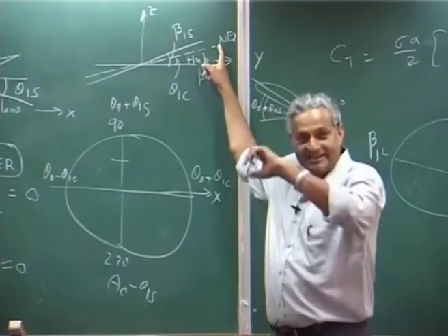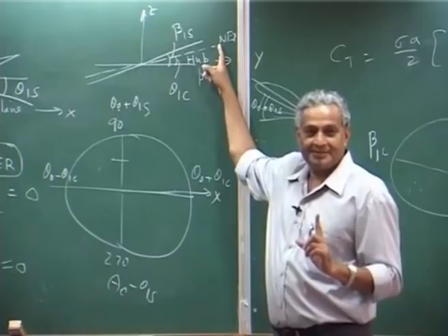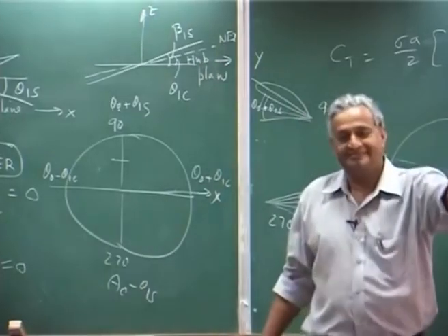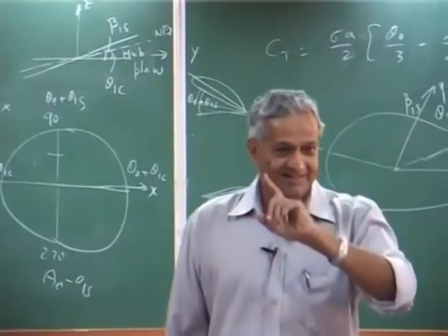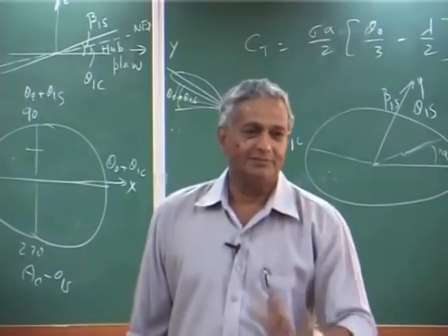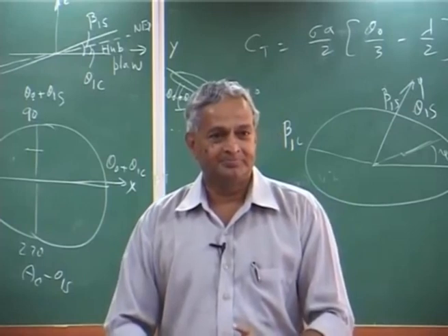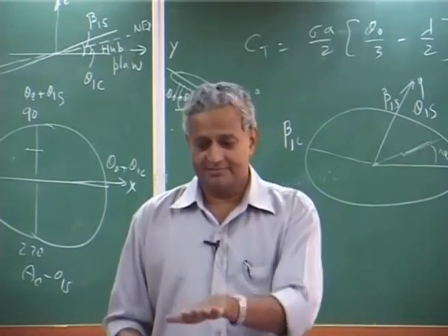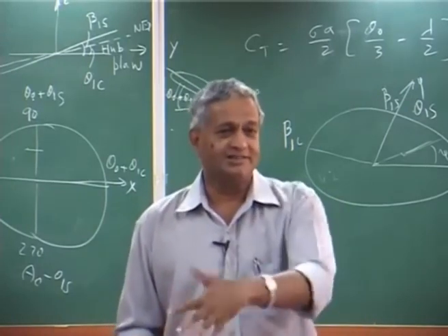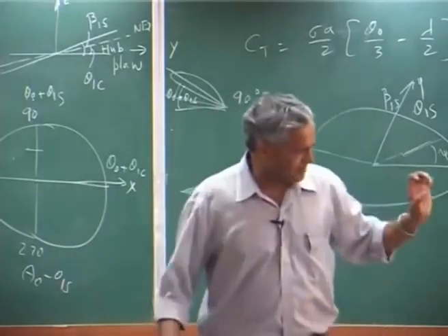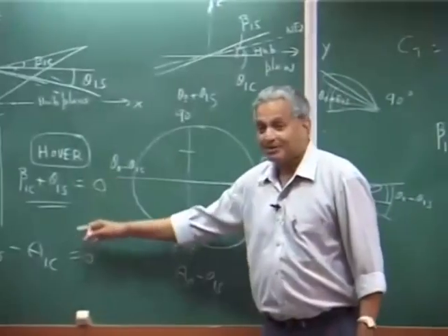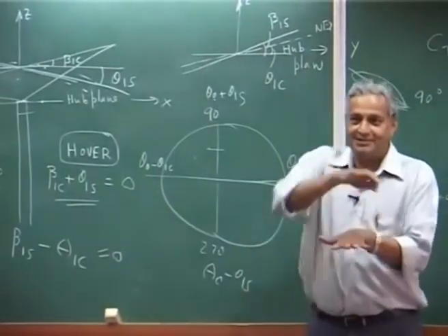And because of the blade dynamics, the tip path plane tilts. Okay. He does not tilt the tip path plane, he tilts only the no feathering plane, that is the swash plate. He just tilts it laterally at any orientation, and as a result, because you know in hover, in the highly simplified case, they are parallel. So, wherever he tilts, that also goes there.